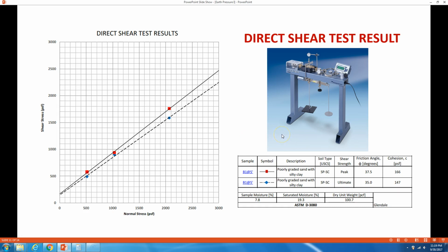So this phi angle that we talked about, where do we get it? When we go to a job site, we take soil samples, and from there it's called undisturbed soil samples in a ring, and we test it in a direct shear test machine, and then we get two envelopes. We get the upper level envelope, which is the maximum strength the soil would see.